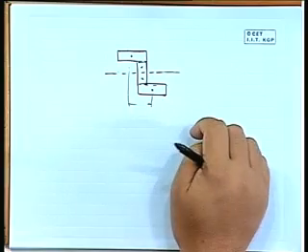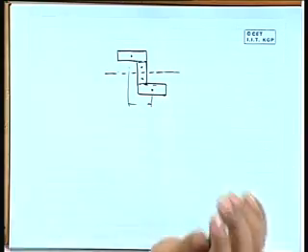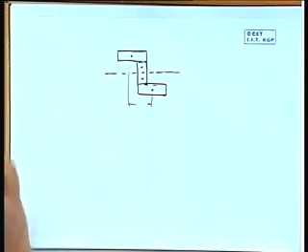Now, if you keep a beam, load is there, there will be a reaction. Externally there is no moment. Horizontally we are not putting any load, but if we just follow the equation My by I, get the stress. From the stress, if we try to calculate the moment, we are getting some horizontal moment. That means there is something wrong in calculating the stress with My by I. My by I will not work here because it is not a symmetrical section.